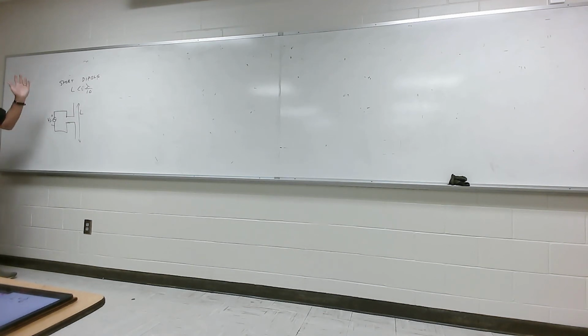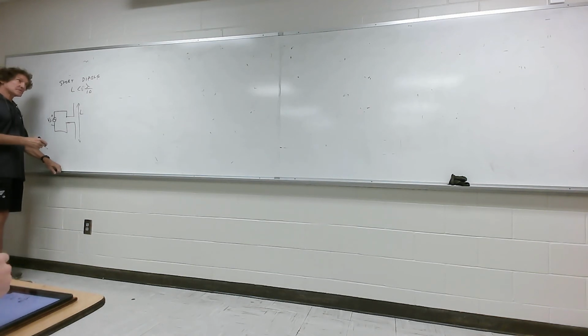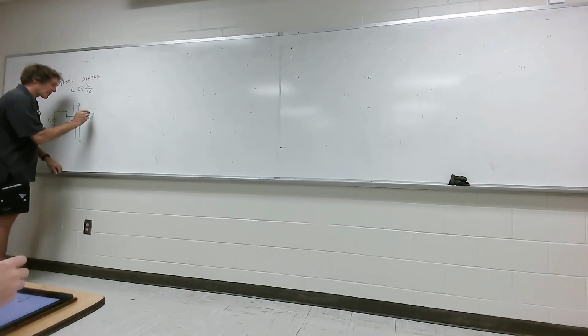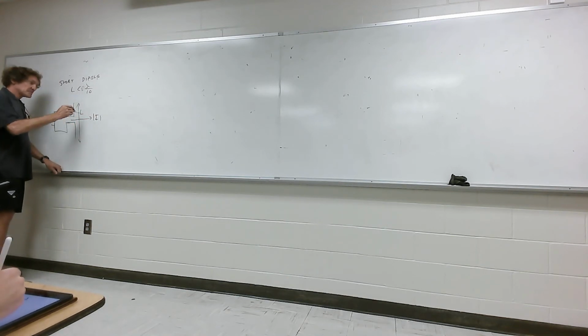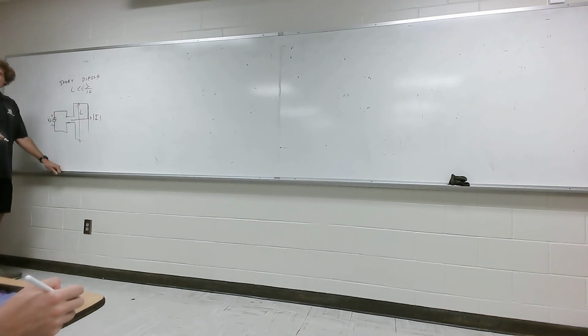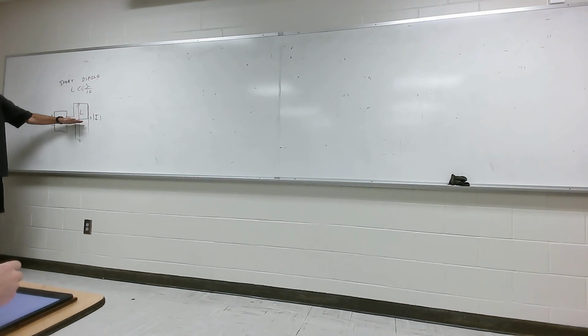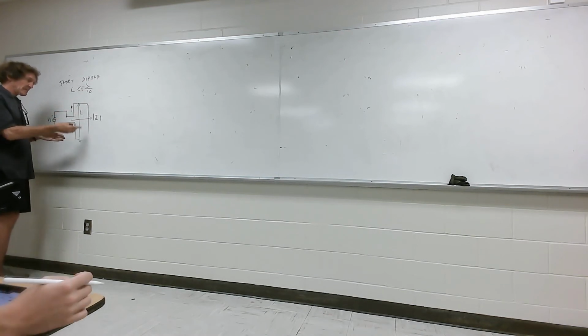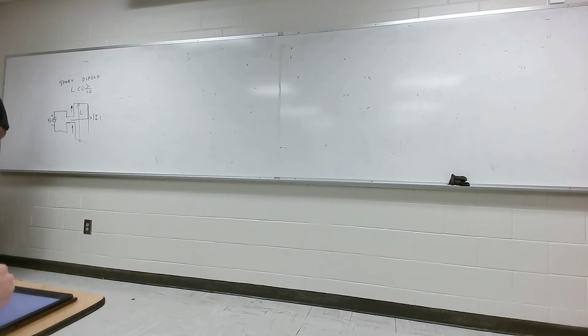This is nothing more than a straight wire. You follow me on this, class? With a straight wire antenna, where L is much less than lambda over 10, a couple of things happen. First is the current distribution. If we graph the magnitude of current versus position, it would be just a constant value. The wavelength's so long that there won't be any kind of standing wave set up. The current's going to go in this direction, and then it'll change, but the magnitude of current will be the same all along that antenna.